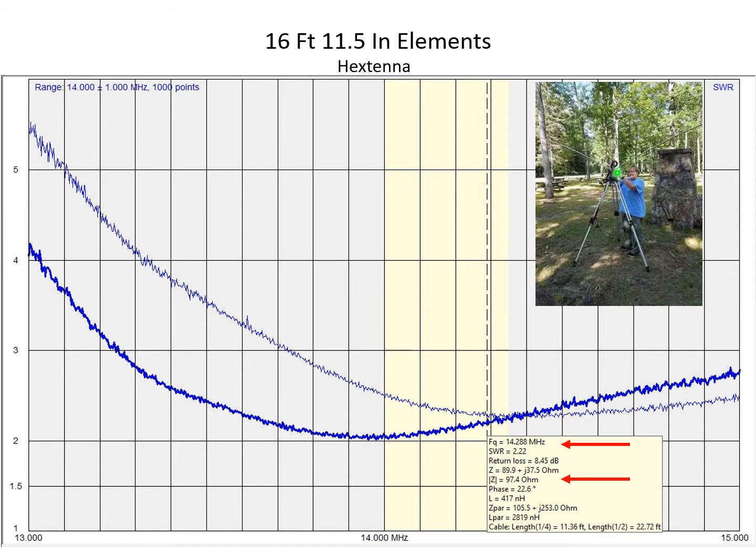And what it is, it's a dipole, a resonant dipole that is made up of two elements, and both elements are telescoping antenna elements that are connected at the midpoint and then tied to the feed line that goes back to the transceiver.